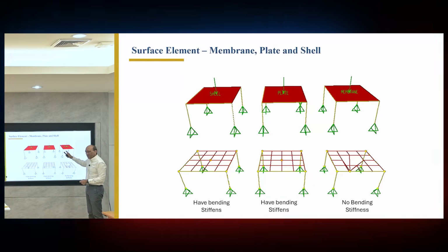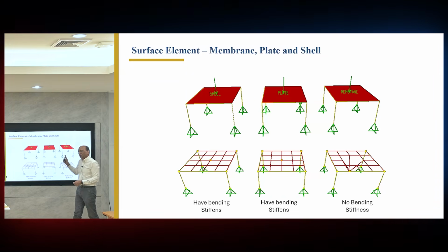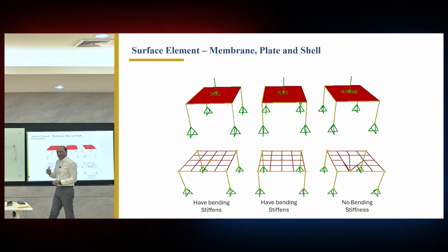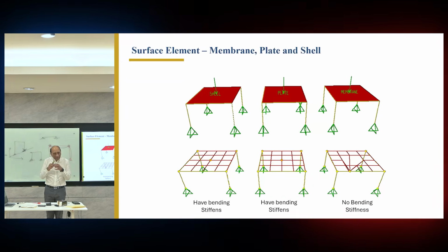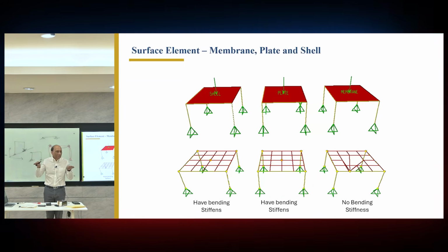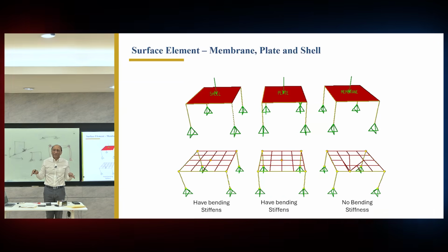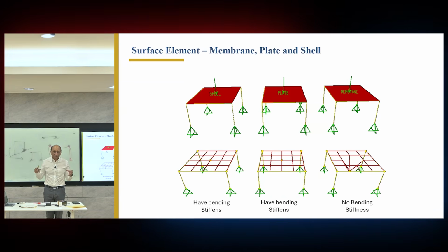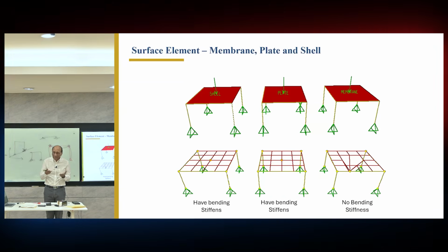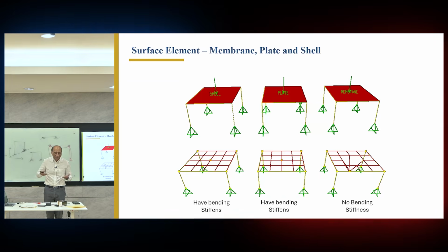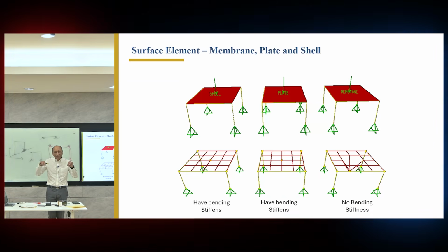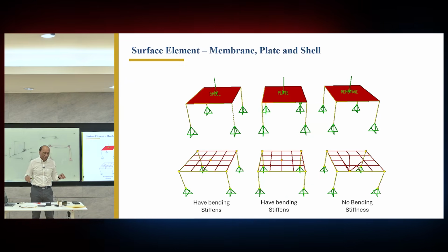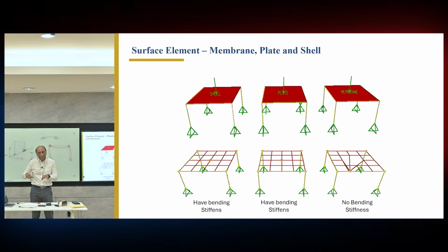But the confusing thing is that ETABS used to use membrane in the beginning to model the floor. But then they transfer the load manually to the beams, like the geometry-based load transfer I showed you earlier. So they use the membrane only to make the floor stiff in plane, but they use manual load transfer for the beams, and do not apply the load to the membrane.